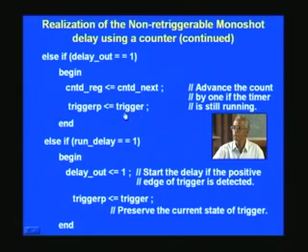And we should not forget to put the current trigger value as the previous value, so as to use it in the next clock when it strikes. This is the previous status of trigger registered here. We are remembering the trigger's previous status by pushing the current value into the previous register. That's what we have put here.